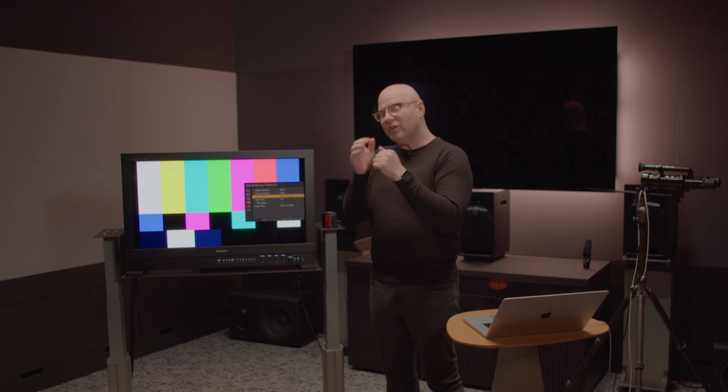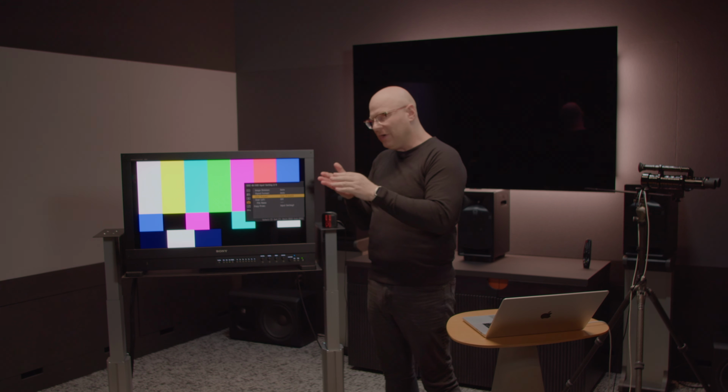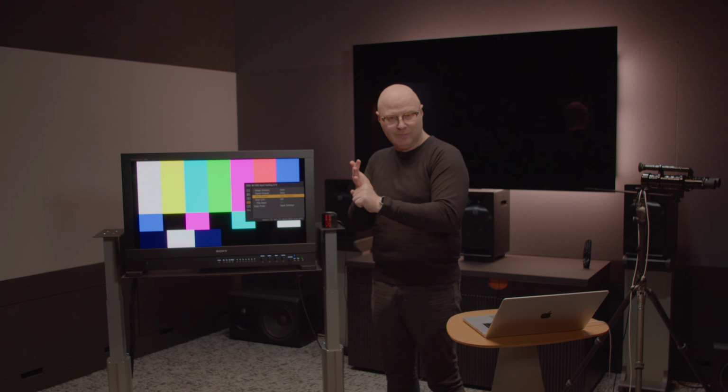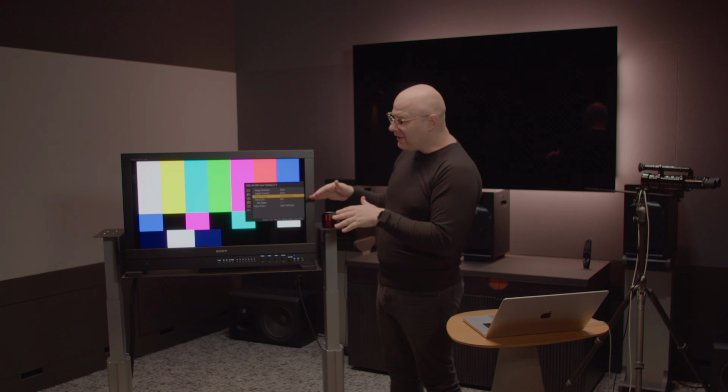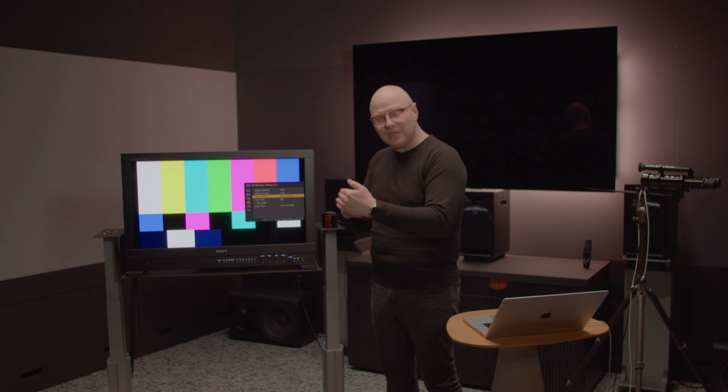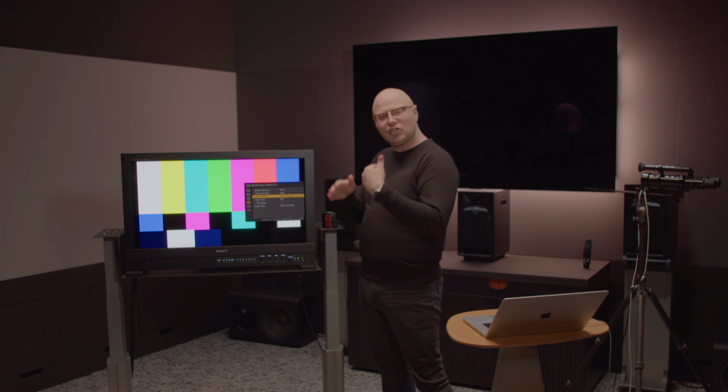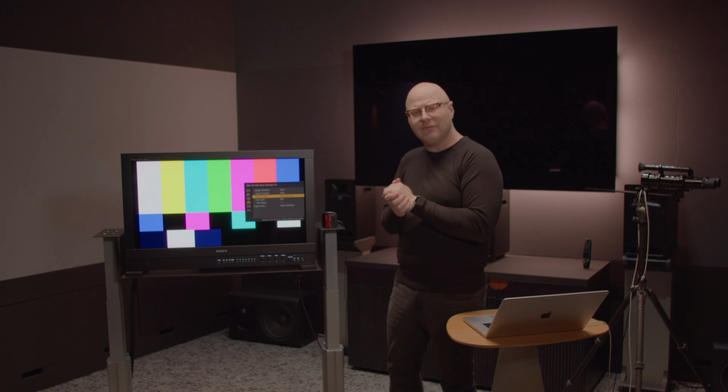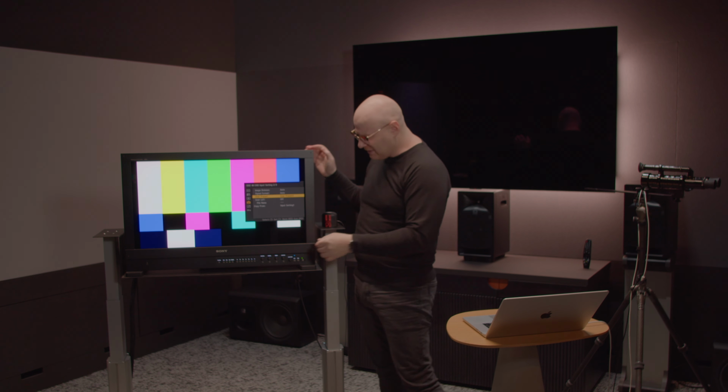Again, because the Sony is going to convert color spaces, what we find is that if you calibrate, say, 100 nits of luminance for 709, that P3, that 2020 at 100 nits is all going to be converted very, very well, very, very closely. If you're in HDR mode, closer to that 1000 nits, you'll find that you'll want to use a separate calibration because the higher light output does change some of the color characteristics of the display. We find that with almost every display.